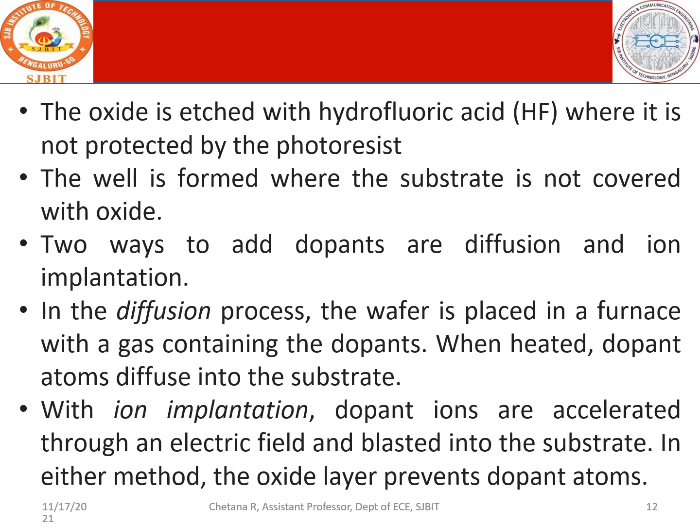After the well is created, you need to create the diffusion into that well. A depth is created. A well is nothing but a deep layer that is excavated. And there you need to create the necessary dopants, or you need to do diffusion with either positive charge carriers or negative charge carriers, thus forming an N well or P well.